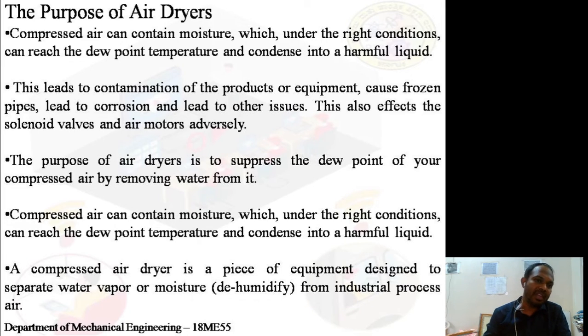As we just mentioned, under the right conditions the compressed air can reach the dew point temperature and condense into a harmful liquid. It is a harmful liquid for the operation of pneumatic systems, my dear friends. This leads to contamination of the product and equipment. It can cause frozen pipes, corrosion and other performance problems.